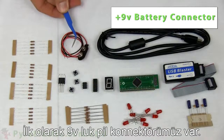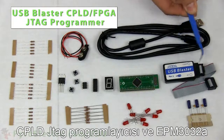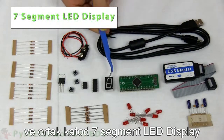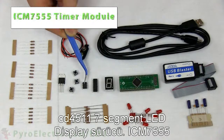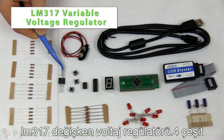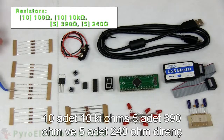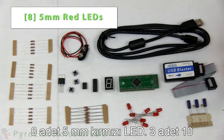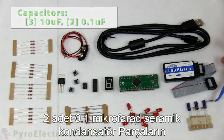And now, let's go through the specific parts from the Components kit. First, we have a 9-volt battery connector, USB cable, CPLD JTAG programmer, an EPM3032A CPLD breakout board with JTAG header, a common cathode 7-segment LED display, CD4511 7-segment LED driver, ICM7555 timer module, 3 tactile push buttons, LM317 variable voltage regulator, 4 different types of resistors, 10 100 ohm, 10 10 kilo ohm, 5 390 ohm, and 5 240 ohm resistors, 8 5mm red LEDs, 3 10 microfarad electrolytic capacitors, and 2 0.1 microfarad ceramic capacitors.